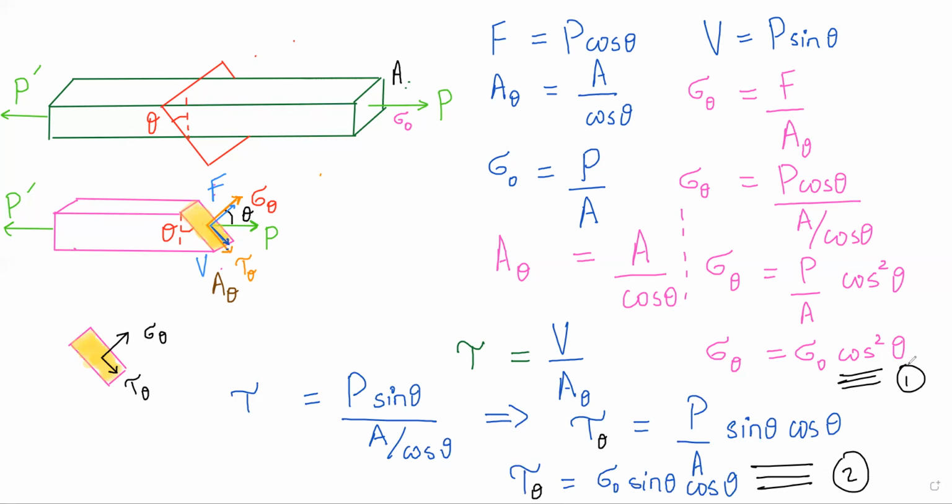Now, if you look at this one, I was pulling it, right? I was pulling it. When you talk about this surface, the normal stress we know. What is the shear stress acting on this? 0, right? Are you following me? So there is no shear stress on this plane when I'm pulling it. This calculator is definitely going to break, by the way. I keep on pulling it, no shear stress. But if I make a cut at an angle, you see shear stress starts to appear. You see that, right? So definitely it makes sense that different sections are of importance to me, because right now there was no shear stress on this plane, but at certain angles, shear stress does exist in this object. So what I will do is, I will now go to the next slide and I will make a beautiful plot.